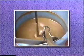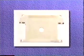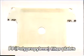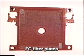Countless different types of slurry can be processed using filter presses. The operating conditions vary depending on the type of slurry. KURITA produces a wide selection of filter plates and compression membranes to meet specific customer needs. KURITA's polypropylene filter plates are only about 1/4 the weight of cast iron filter plates. They also feature excellent chemical resistance and durability. KURITA's cast iron filter plates are ideal for very high temperature slurry and are the perfect choice for the refining of vegetable, animal, or mineral oils.